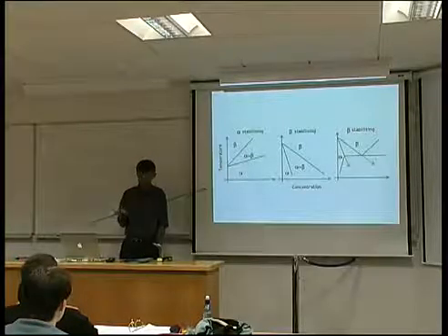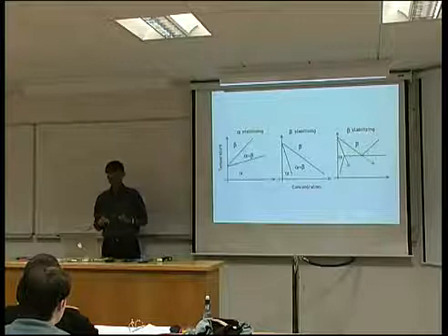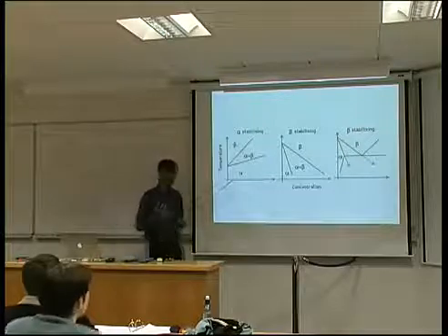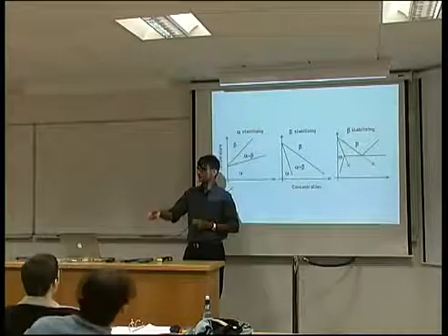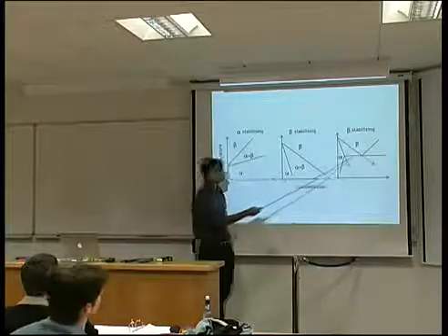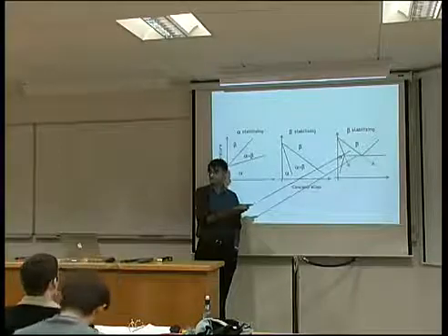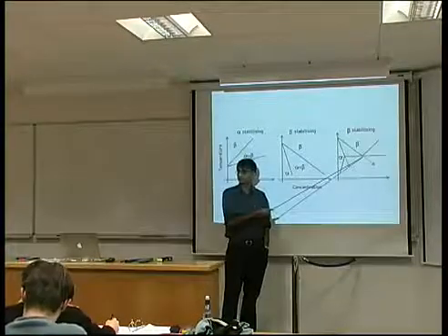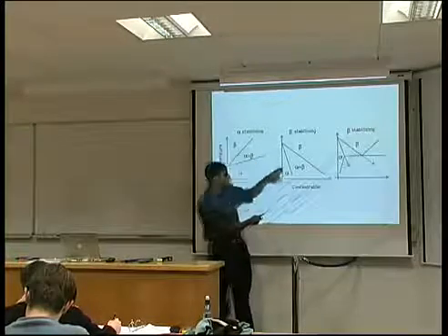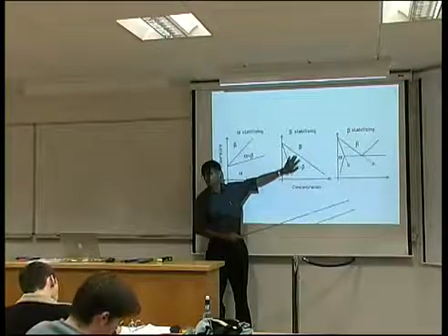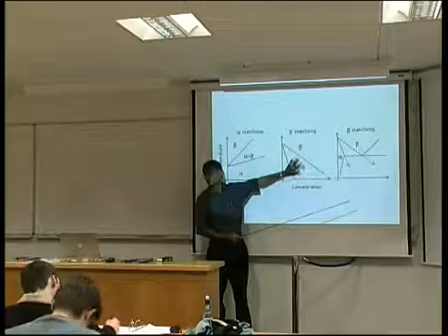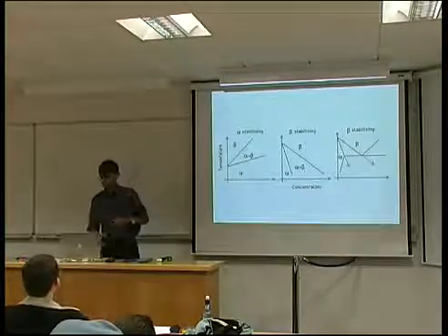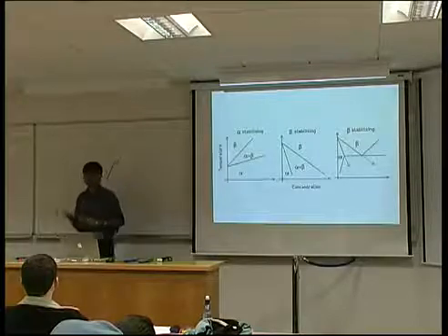You know, pearlite in steel I can form at a really low temperature if I want to, and it forms very rapidly. Exactly. So in the case of pearlite in steel, it's carbon that is diffusing to form the eutectoid. But here we would have substitutional elements diffusing to give us the eutectoid reaction. So very frequently, even though this is a eutectoid phase diagram, we don't actually get a eutectoid, and the whole phase diagram behaves as if it is like this. So you can suppress the eutectoid reaction even at relatively slow cooling rates, because it requires the diffusion of substitutional atoms.